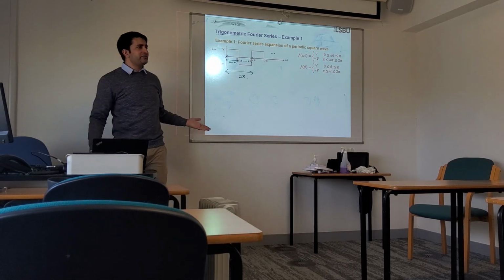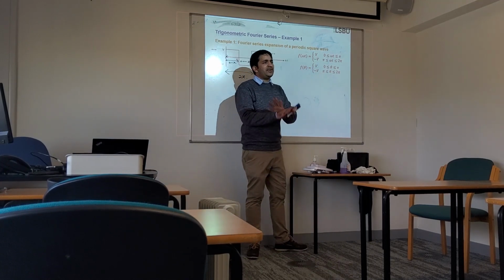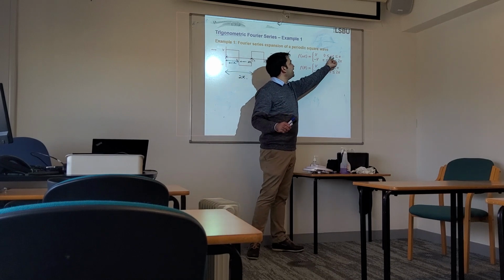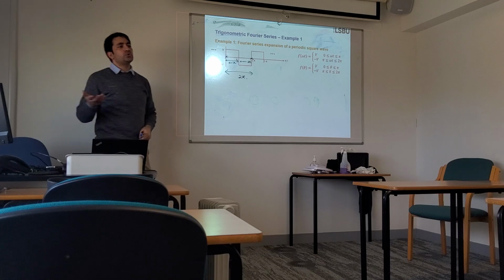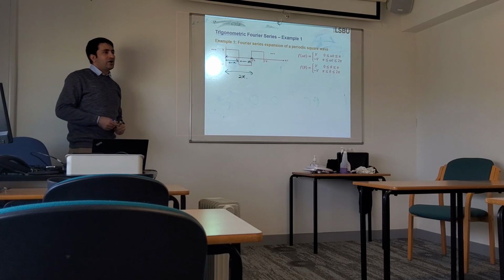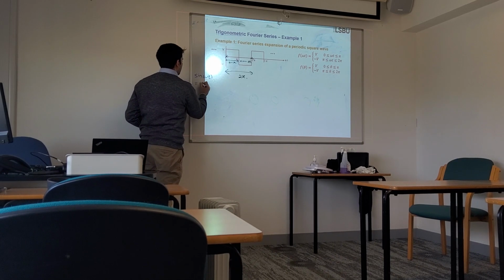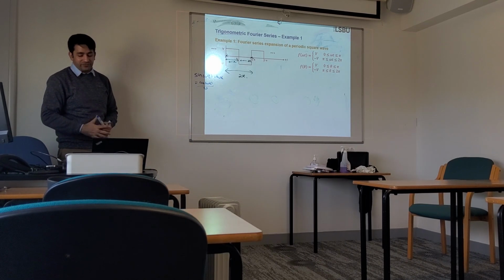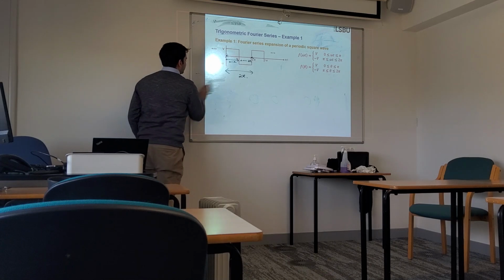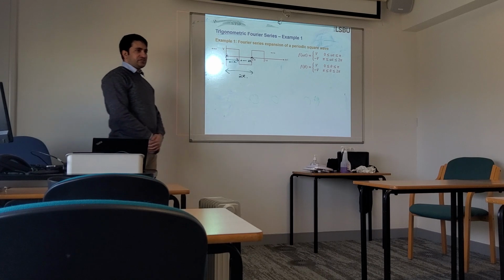As I said previously, for the sake of simplicity we have replaced omega t with theta. It will not affect your calculation because your variable is completely omega t. So simply replace omega t with theta so that you don't make mistakes during calculation. Sometimes you will see sine of omega t written as cos of omega t divided by omega, which is not true. Why? Because your integration is with respect to omega t; the whole omega t is your variable. That's why in the second step we replace it with theta, so now we have the function f of theta.